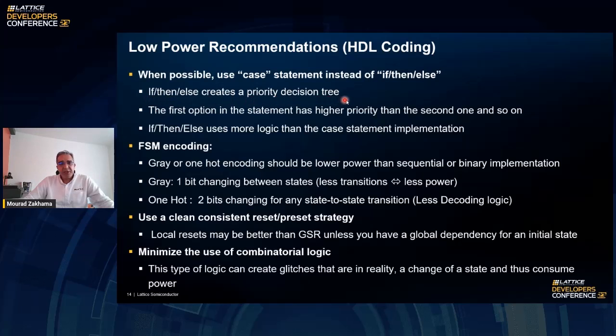I mean, usually these happen if there are undefined cases. Then all the others will have lower priority and will create extra logic and will generate a priority tree, and that's extra logic levels generated based on the way you write your HDL code.